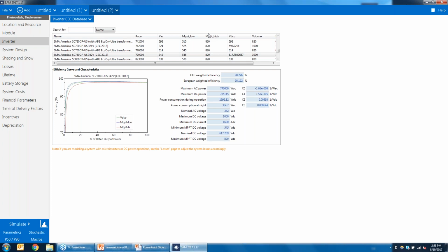In general, though, the farther apart your modules, the more power you're going to produce. There isn't some type of parabolic curve as far as row spacing is concerned. So basically, the optimal system, just from that respect, is going to be at your maximum row spacing within a given system size. But if it causes you to change system sizes, which is what I imagine you're getting at, then there is probably some type of balance between system size and spacing.